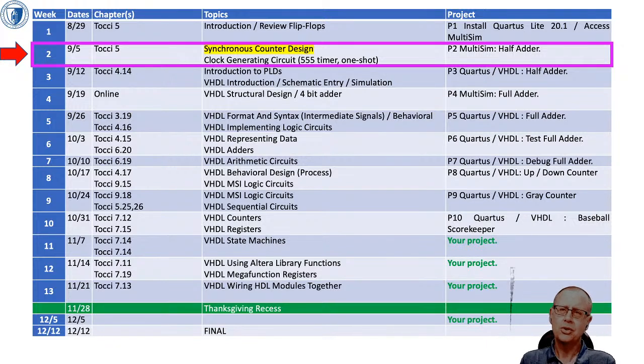Here, in logic design, the synchronous piece means that there's a fundamental clock signal, right? An oscillating clock signal. It's going between 0 and 1 at a specified, constant rate, and that's driving what's happening in the rest of the circuit. You can have asynchronous digital circuits, and we'll talk a little bit about that, particularly with JK flip-flops. They have a synchronous aspect and an asynchronous aspect.